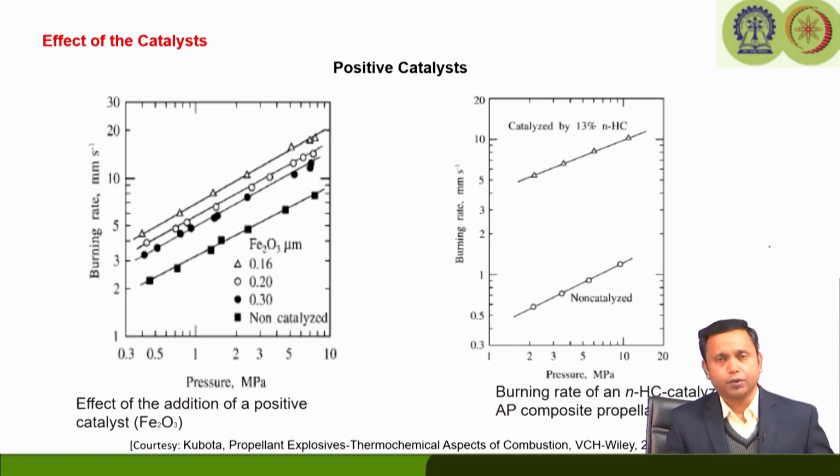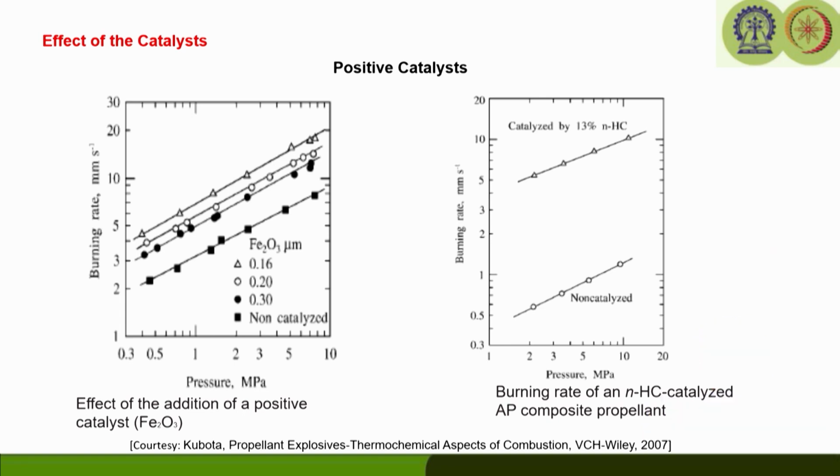Okay. Now, what we should remember is that the diffusional mixing between the gaseous decomposition products and the AP particles determines the heat flux feedback coming from the gas phase to the condensed phase, if you recall the typical flame structure of composite propellants.